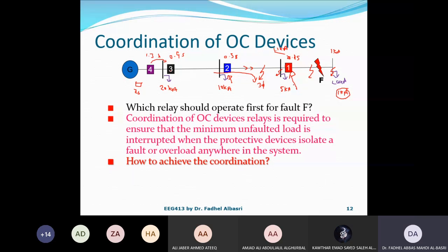So this relay can guarantee the fault is in this line if the fault exceeds 1 kilo ampere by, let's say, a 25% margin. So if the fault current is greater than 1.25 times the fault current at the remote bus, then it is a fault in this line, and you can act. We don't have to wait.